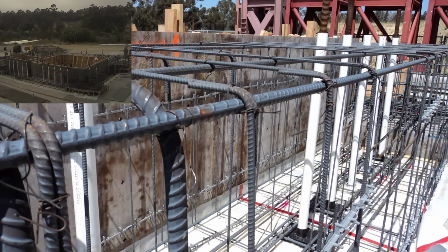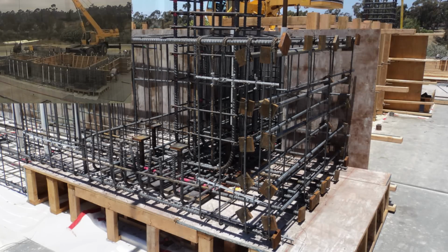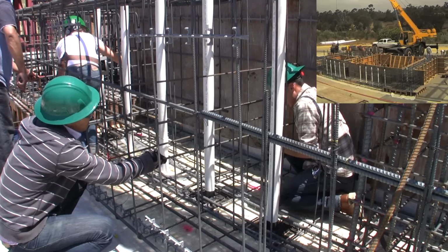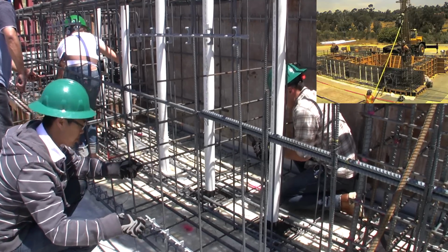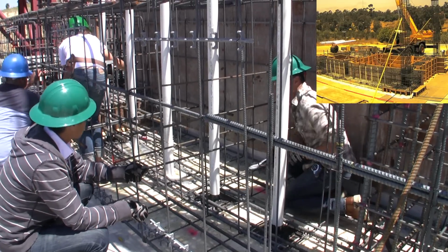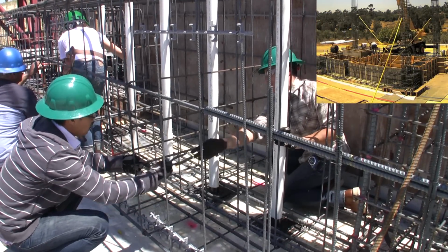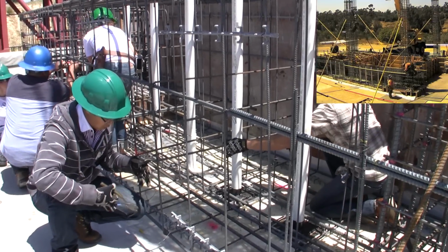to carry the tension forces, since the strength of concrete in tension is only 10–15% of its strength in compression. Specifications for the design, materials and placement of a reinforced concrete section are governed by guidelines developed by the American Concrete Institute. After the construction of the foundation formwork is complete, rebar cages are installed. Rebar cages can be built either on or off site and then placed inside the foundation formwork. In this project, the foundation rebars were built on site.